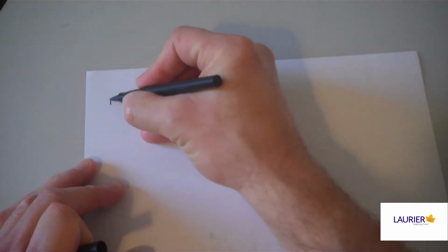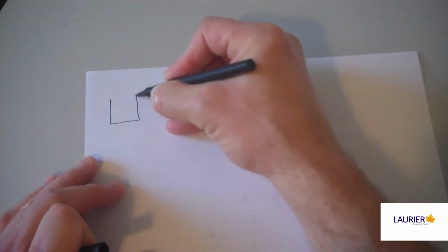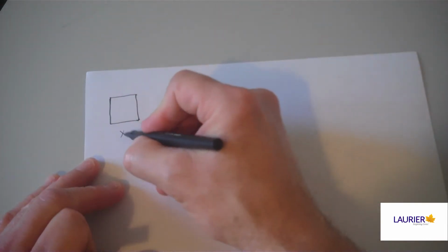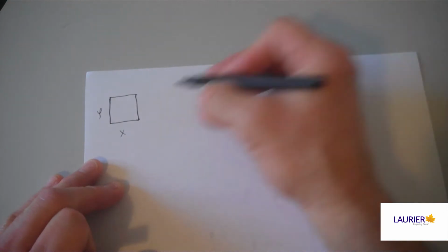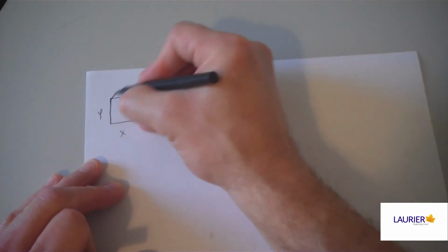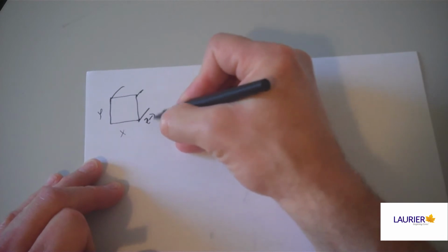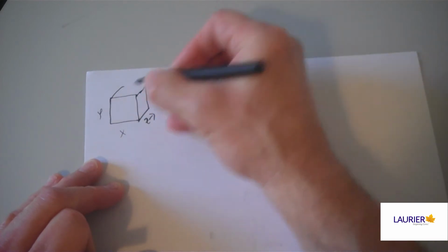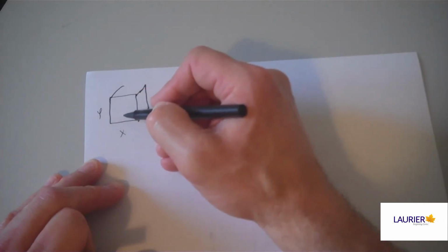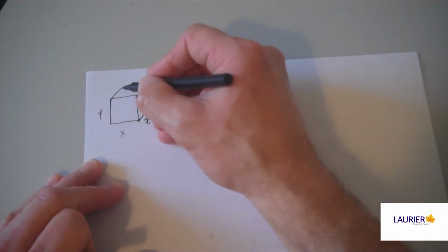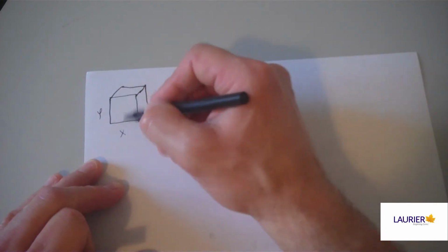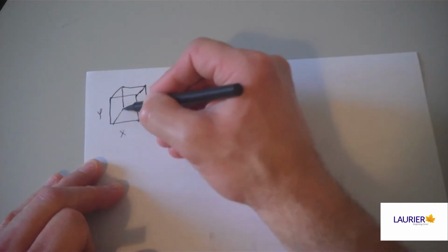To draw an extruded part, you can take a shape, and in this example we make a nice square here. We'll draw it on the XY plane. We then drag the shape through space along the Z axis, and because the two-dimensional shape closes in an area, as we move it off the plane it was drawn on and through space, it encloses and captures a volume. That's the most common way we make a 3D object in SolidWorks. We make a two-dimensional drawing into a three-dimensional virtual solid by moving it normal to the drawing plane.